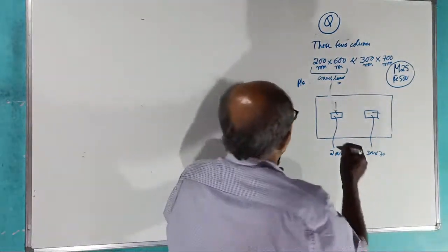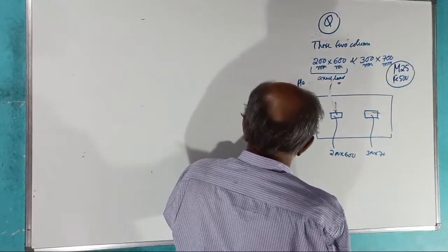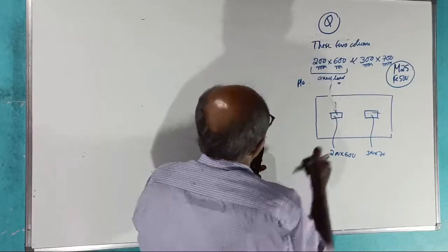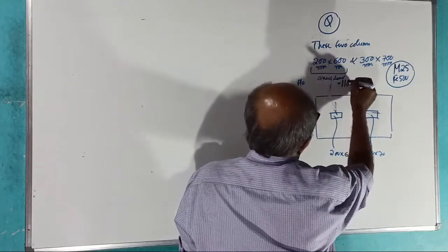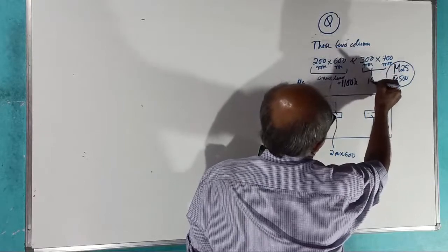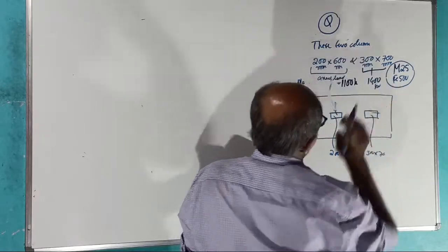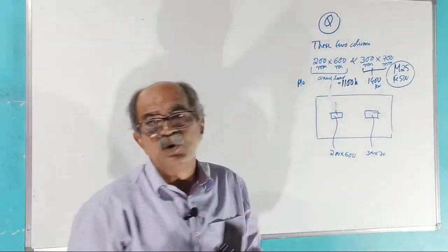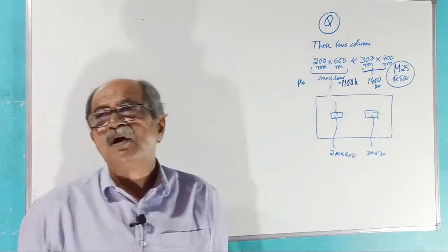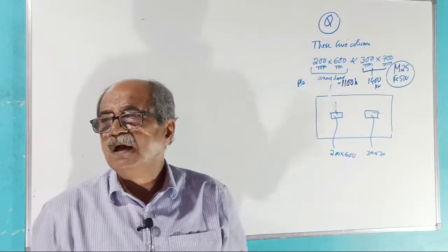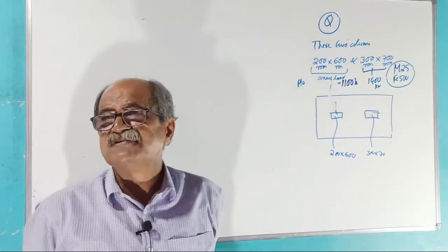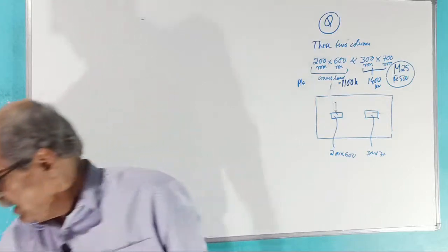Okay. Then axial load is, first column is 1100 kilonewton. Second column load is 1400 kilonewton. Okay. Now, also I am taking quite a good load for a building of around ground plus 3 or 4. Remember, if it is only 1 floor or 2 floors, the load will be lesser. I am taking quite heavy load.